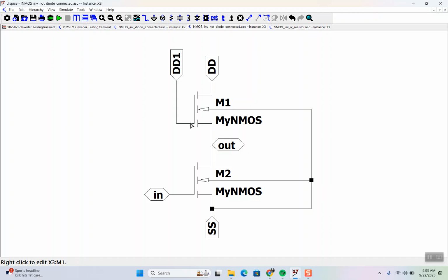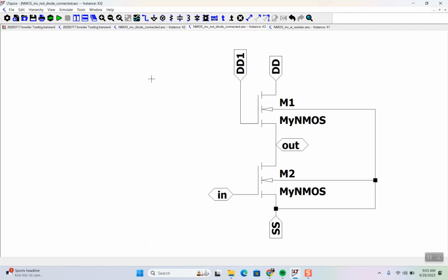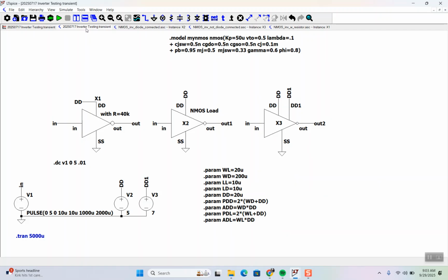And so then you can have 130 nanometer devices, PMOS, NMOS, memristors, and 5 layers of metal. This really is beyond what can be easily done at a university. So we stick to the 4 masks. Sometimes we even do 2.